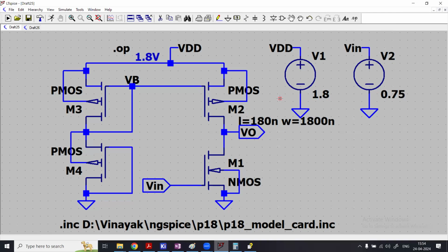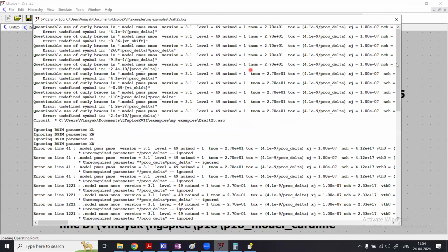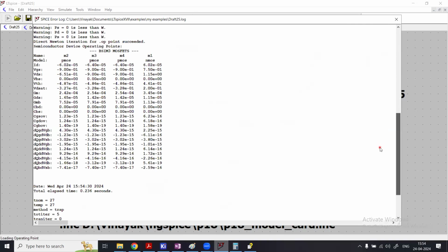Now from the simulation, we have got the value of GM. Did we note that? Let us note the value of GM. So we'll not take into account these parameters. Rather, we close it, and take the values we get from the SPICE. So we have to note the parameters here. Write down VO divided by Vin, which is what we want actually. So here VO divided by Vin is GM1 times RO, and RO is RO1 in parallel with RO2.